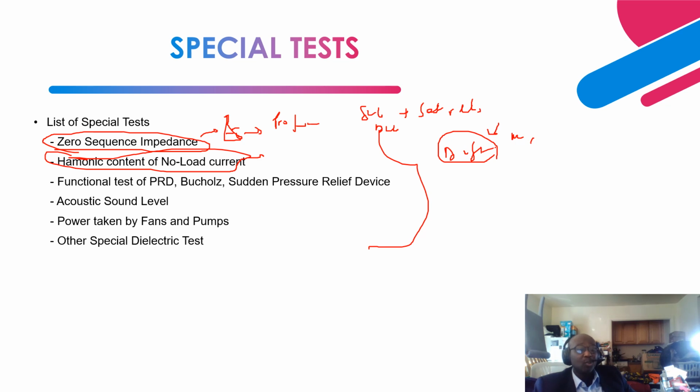So what some of the customers do is they tell the manufacturer, you need to provide me the harmonic content of the no load current: the second harmonic content percentage-wise, fourth harmonic, third harmonic, fifth harmonic percentage-wise, so that I can use it to set my magnetic inrush inhibits to prevent nuisance tripping. Let's say after the testing this one is 20%, this is how much inrush. So based on that, the relay engineer will do his setting.